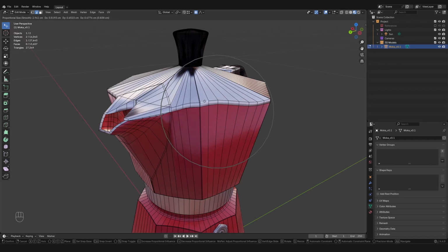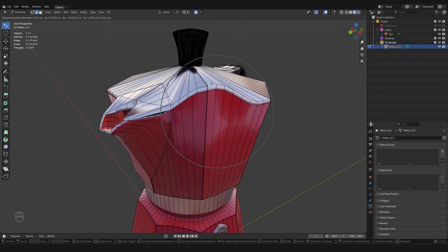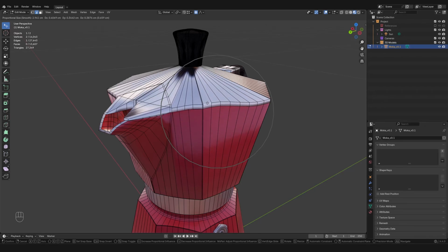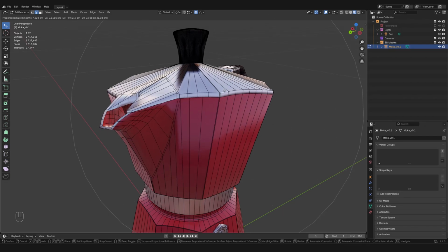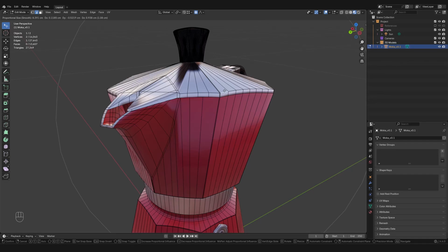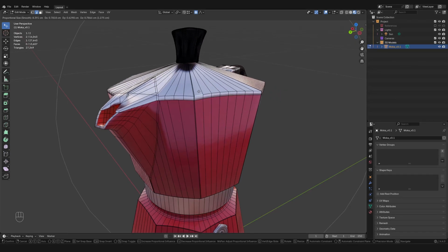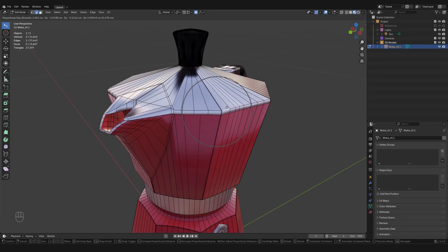And this is all live, right? So I've started my G command, but I've not yet left-clicked or right-clicked away. So this is all a live preview. And if I scroll with my mouse wheel, I can expand my radius, and you will see that more and more edges get affected by this change. Or I can make it way smaller, and then I'm localizing my change.